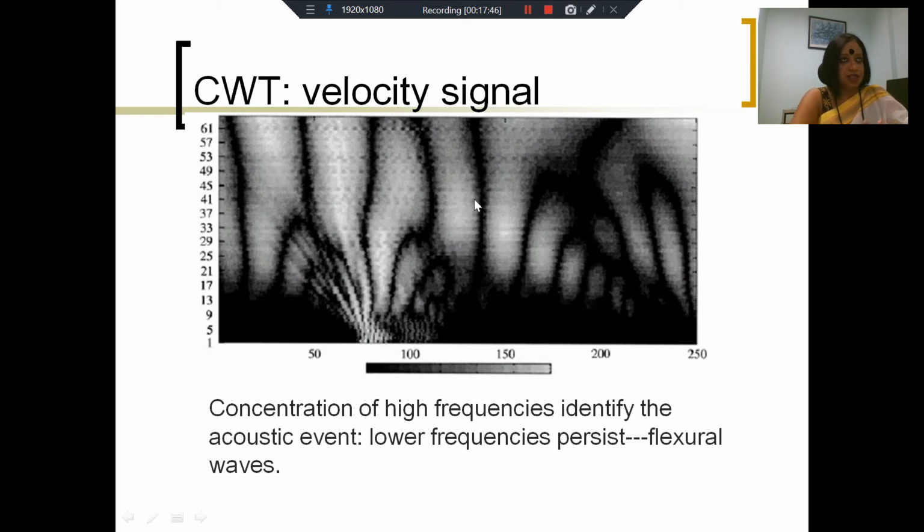If you look at the research on partial discharges, you will see that, if you remember, even for electrical signals, I said that there are only certain hardware techniques that you can use to filter out the noise. But there will be some noise still left, and then we have to employ software techniques for eliciting the data in a better way. One of the techniques that you will routinely see employed in the research on partial discharges is the wavelet technique. I will not go into the details, but I will tell you how wavelet analysis can help you in eliciting information from the wave, which can help you locate the discharge.